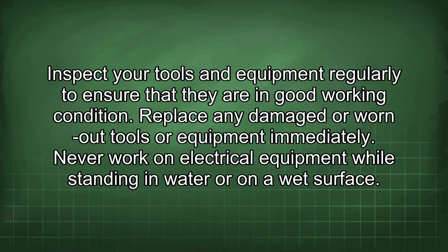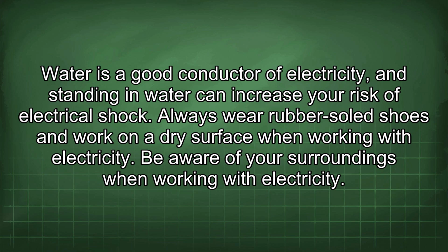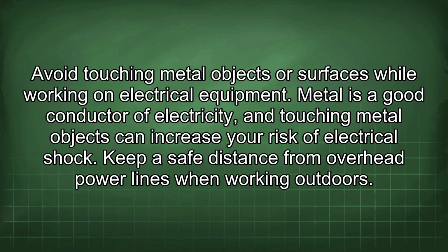Never work on electrical equipment while standing in water or on a wet surface. Water is a good conductor of electricity, and standing in water can increase your risk of electrical shock. Always wear rubber-soled shoes and work on a dry surface when working with electricity. Be aware of your surroundings when working with electricity. Avoid touching metal objects or surfaces while working on electrical equipment. Metal is a good conductor of electricity, and touching metal objects can increase your risk of electrical shock.